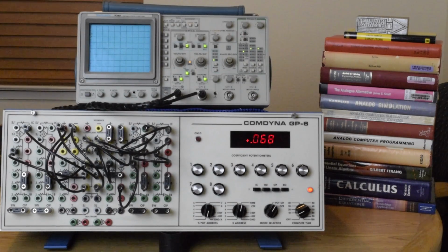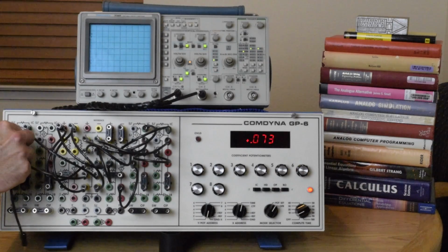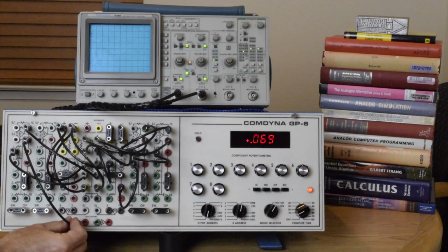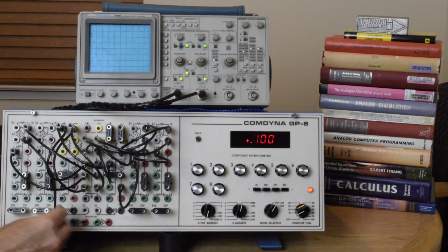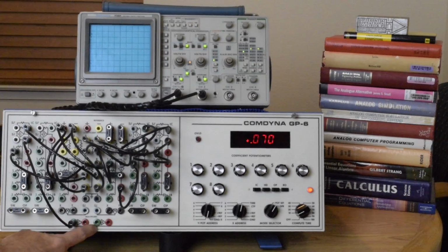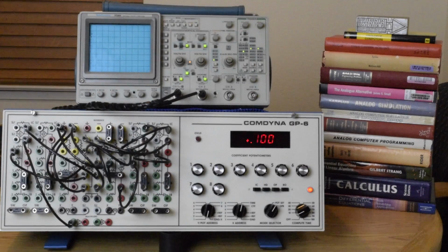Now, an interesting fact of the analog computer is that all of these computing elements also invert their output. That's just the nature of the amplifiers in an analog computer. So to make things easier, I'll take the output of integrator 1 and apply that to the input of this inverting amplifier, which simply re-inverts the output. So on the output of amplifier 7, we'll have the true output.